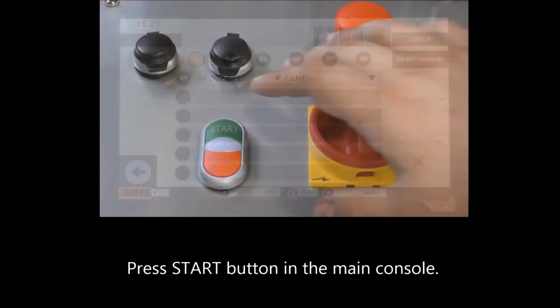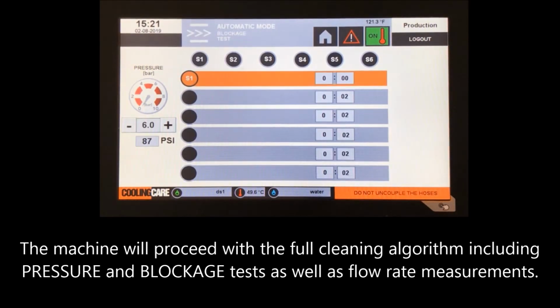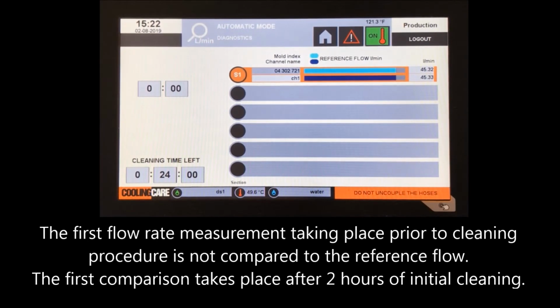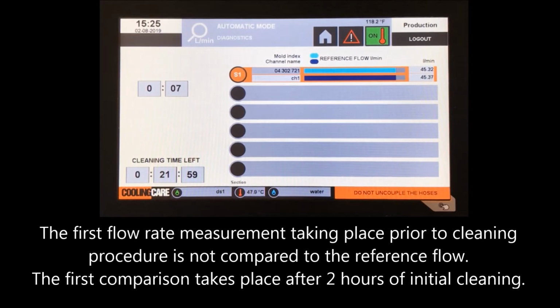After that time, the process is finished. Press the Start button in the main console. The machine will proceed with the full cleaning algorithm, including pressure and blockage tests, as well as flow rate measurements. The first flow rate measurement, taking place prior to the cleaning procedure, is not compared to the reference flow. The first comparison takes place after 2 hours of initial cleaning.